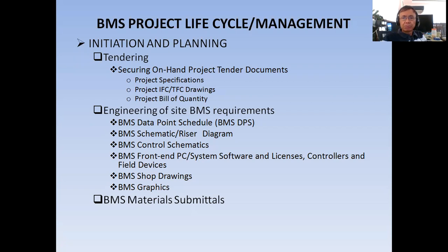Now, I already explained in my previous video how you are going to define and finalize your BMS data point schedule, because in this DPS, you will be able to see or select your controller and your field devices. So if you already know your total BMS data points, then you can also select the system software. The points requirement you should consider, especially if you are defining your software licenses.